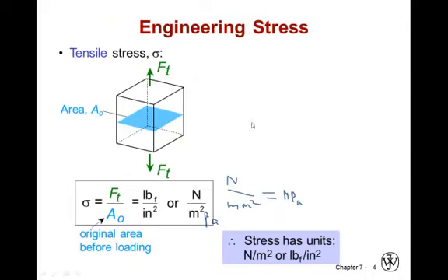Engineering stress is referred to as engineering stress versus true stress. The actual area does change, but most of the time we are considering the original area. So the tensile stress is represented by the Greek letter sigma, and it refers to a force that is distributed over an area, and this force is perpendicular to this area. So the stress is the force divided by the area,